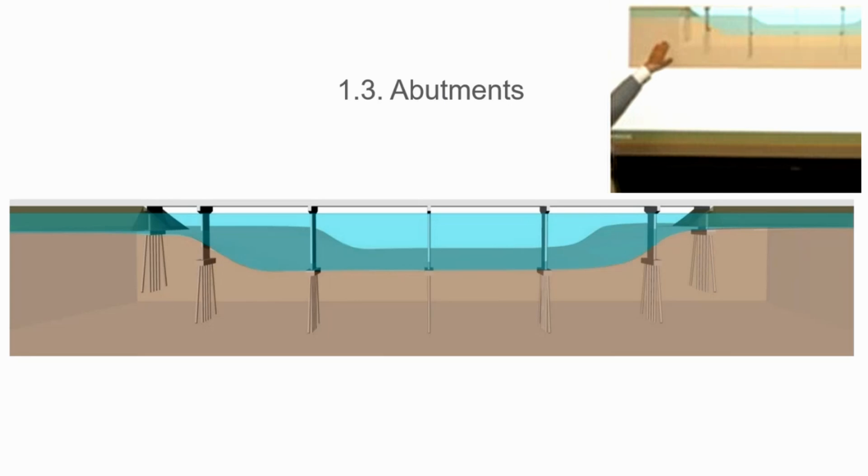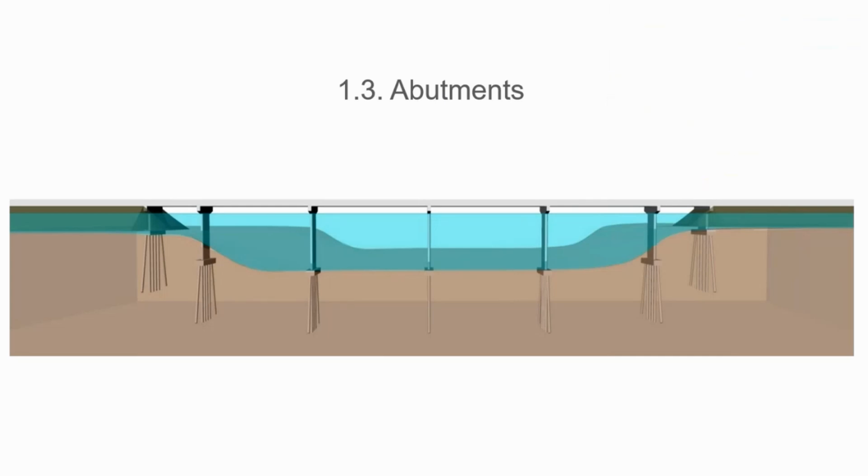As you move toward abutments, we have to consider typically more the geomechanical effects. Geomechanics, these things, the scour deepens, but the failure is actually a geomechanical failure. There's just not enough support, geomechanical support for the bridge. This is the friction-bearing piles, piers to stand up. On abutments, as we saw with in-stream structures such as Benway weirs and rock veins, it doesn't take much scour to destabilize slopes, and you get these structures failing.